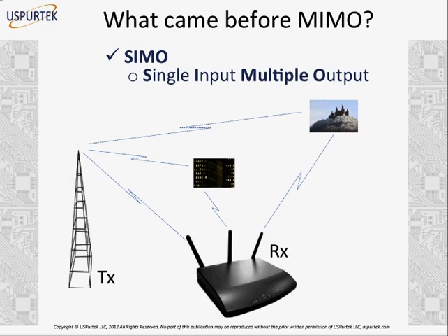So in real life, you see in this picture, I have a radio signal received directly from the transmitter. Then I have another one from a tall office building, which is a reflected signal. So the signal from the tower first strikes the building, and from there it's reflected and then received by the receiver. And a third copy of the signal reflected from the hilltop.